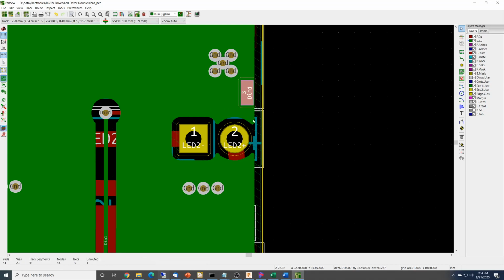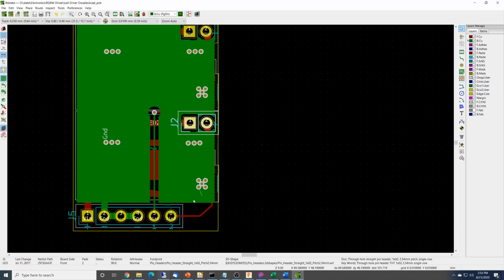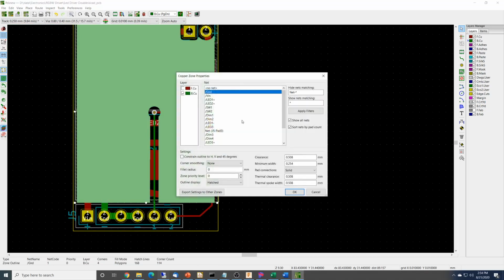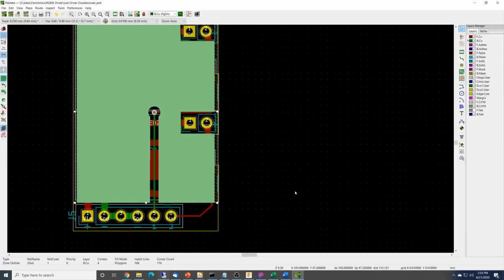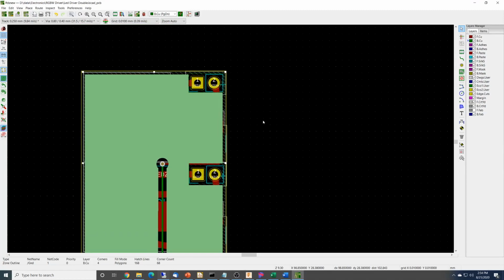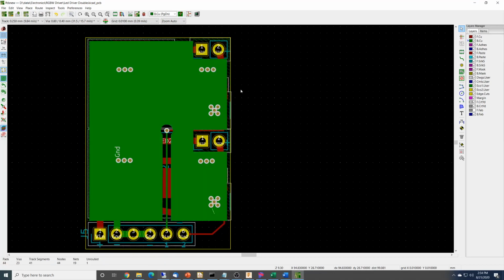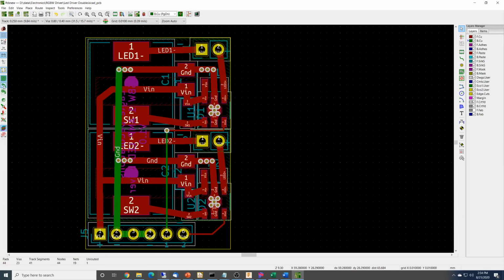One way I know that works is if I select the whole copper pour, hit E, hit OK, and then it did a recalculate on the way out. And you notice now I have space there. Now obviously this occludes most of what I want to see, so I can turn them to hatched. There's also this weird outline mode, which I guess some people like, but I generally just keep them turned off.